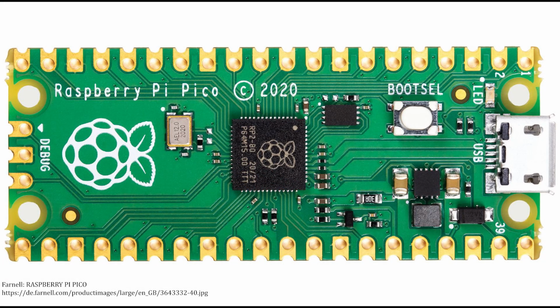To load it onto the Pico, you'll have to connect the microcontroller to a PC while holding down the boot cell button, and then drag the UF2 file onto the Raspberry Pi Pico storage device. For the remainder of your active usage of MahPicoBoi Typhon, you'll have to keep the Raspberry Pi Pico connected to a power source via its micro USB port. You'll know that it's correctly running the MahPicoBoi Typhon code when the green LED lights up.